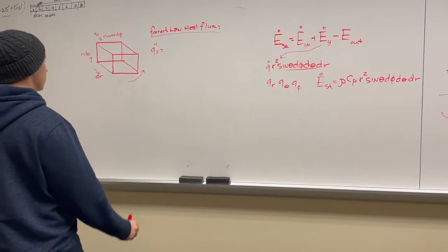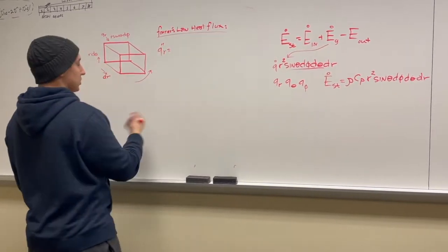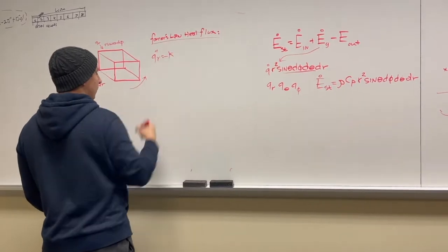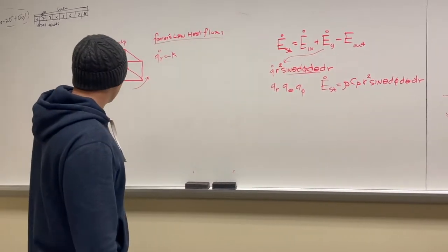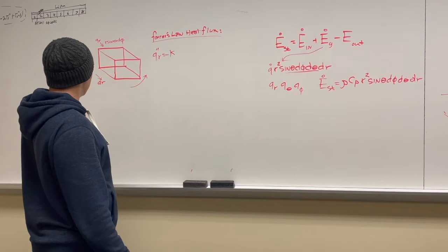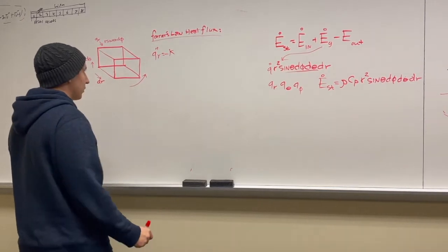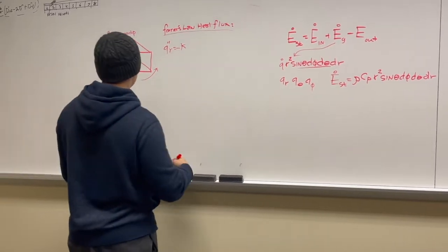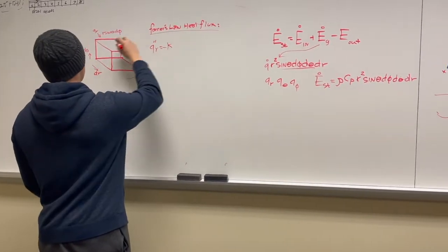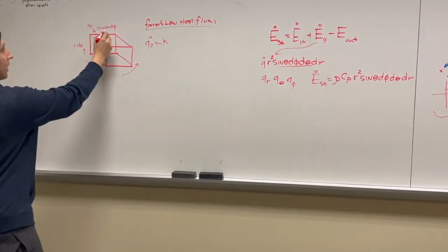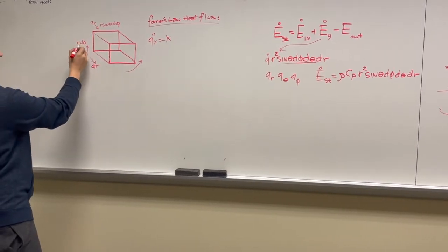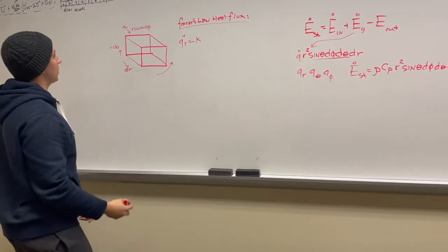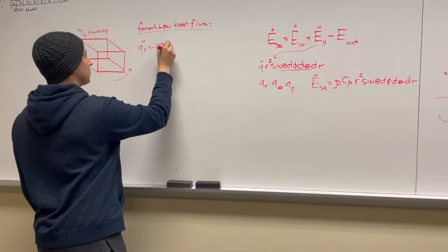They work in differential changes. So as before with the rectangular coordinates, we have the negative of the thermal conductivity of the material that this differential control volume is made out of. And then we have to account for the surface in that direction, the differential one. So we have r sine theta d phi, and we have r d theta. So what we can do is combine those r's to be an r squared.